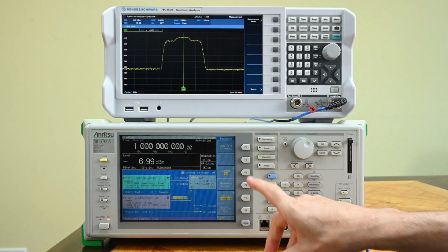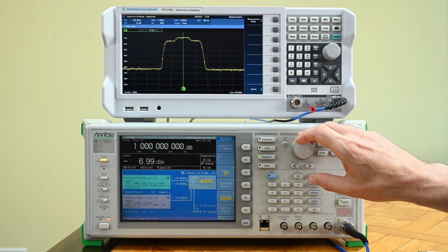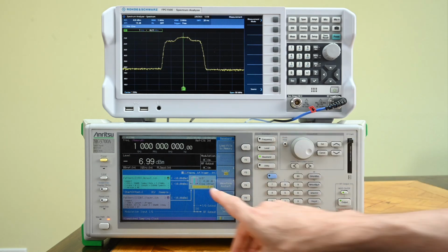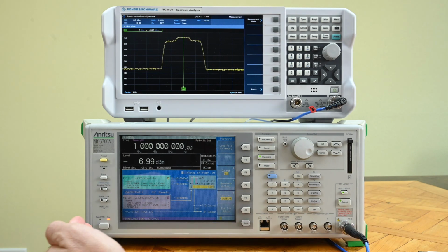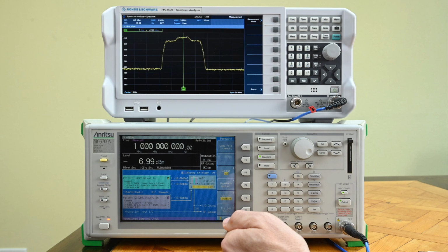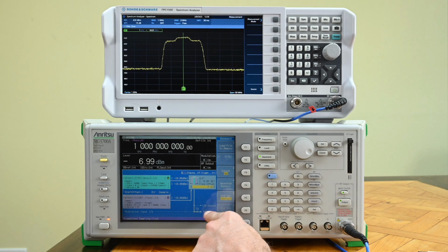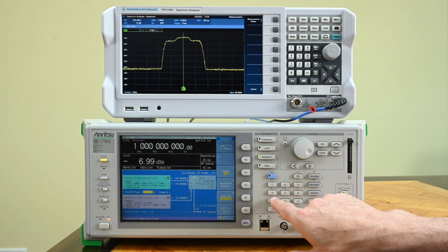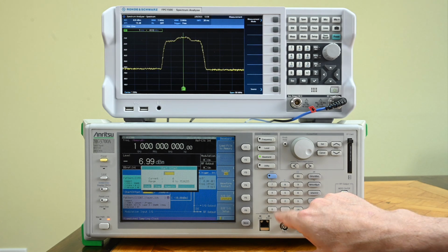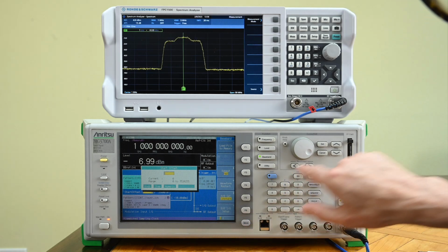And one of the really nice things we can do is change a frequency offset between the two of them. There you go, you see frequency offset. So within the baseband domain, we can already move one of these signals to another frequency, and then the end result is going to be modulated all the way to the RF output on 1 gigahertz in this case. So let us go and try to see that and set a value. And wait a minute, I think I'm in the wrong menu right now. Give me just a second.